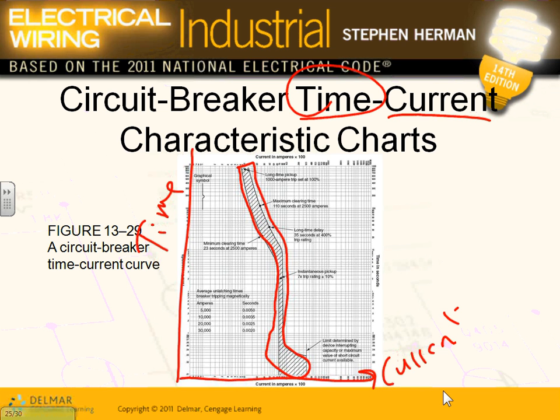Characteristic chart or curve. They call it a curve. And here's your curve. The higher the amp, the faster it trips. The higher the amp this way, the faster the system will trip. We'll look at this example in a second. You have to understand every circuit breaker or fuse or ground fault has a curve like this. That's called the time current characteristic curve.